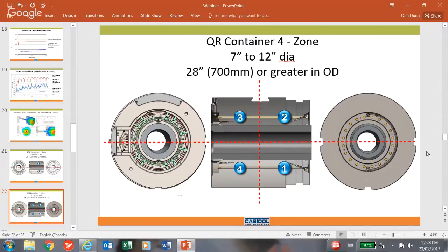The container prior to extrusion will be ramped up slowly, either using a Castool warm-up panel or a set of secondary programming supplied in conjunction with our control panel. This slow ramping of preheat from plant temperature to operating temperature is critical to element life and that of the electrical system itself. This allows for any moisture to be slowly eliminated from the core of the elements prior to the application of full heat and power. The slow ramping also ensures that the shrink fit between the liner and the body is not negatively affected, which could cause premature failure of the liner and/or body.